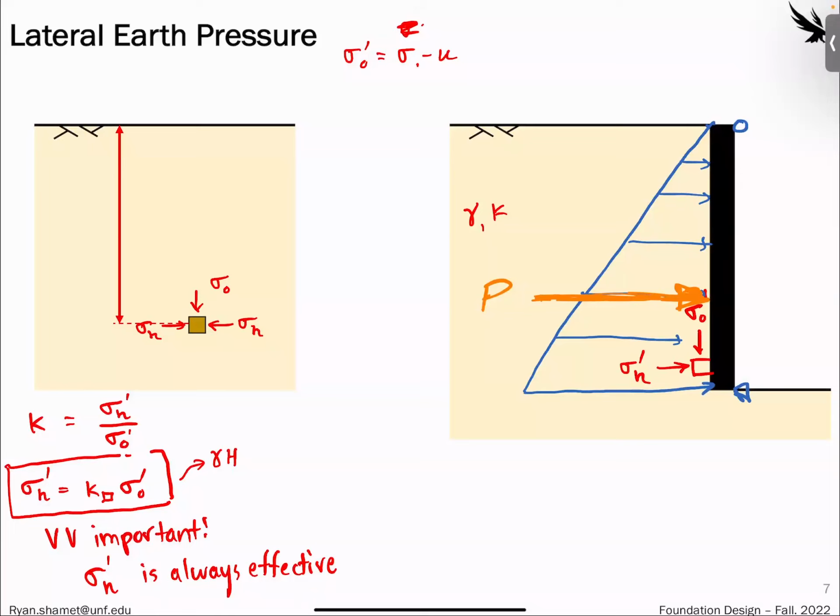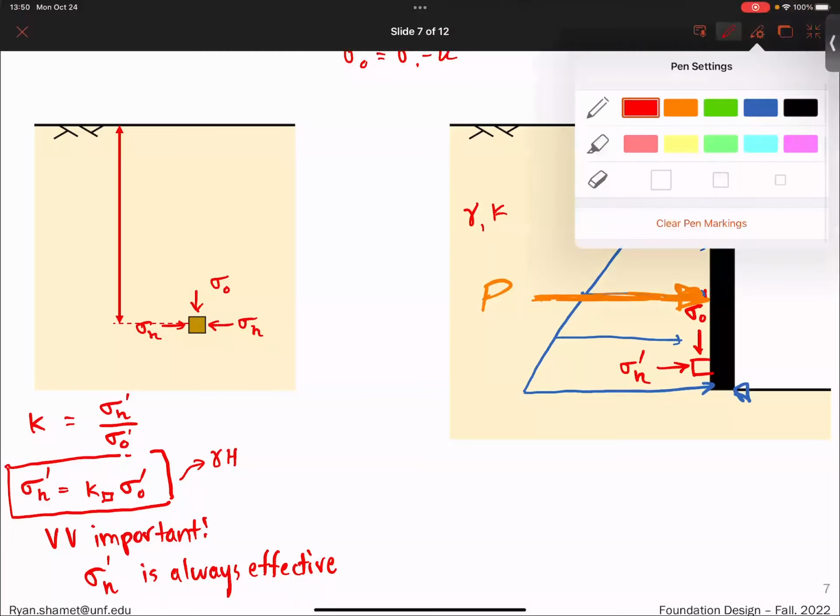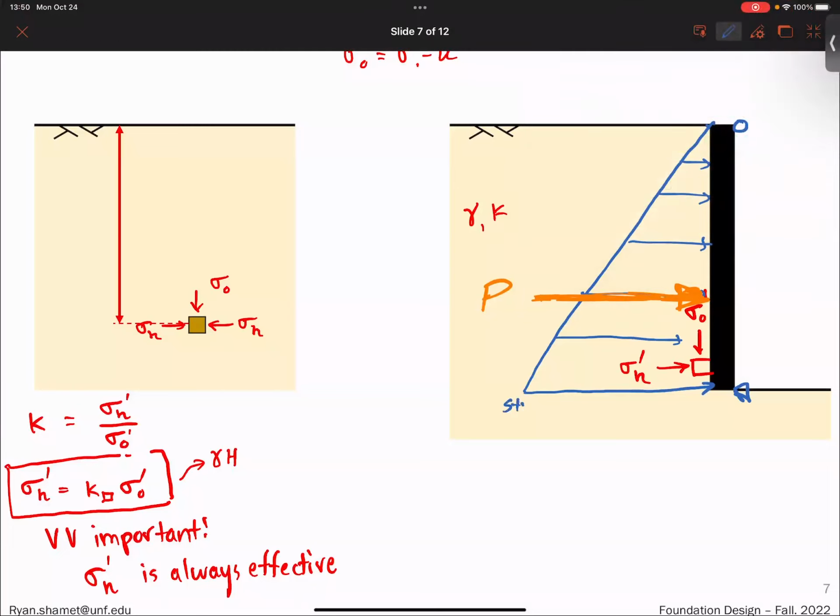So what we would show then is this blue, the stress profile, and that would be important. But then we would also need to find the resultant force. We know if it's a triangle, that's occurring 1/3 of the height from the bottom.